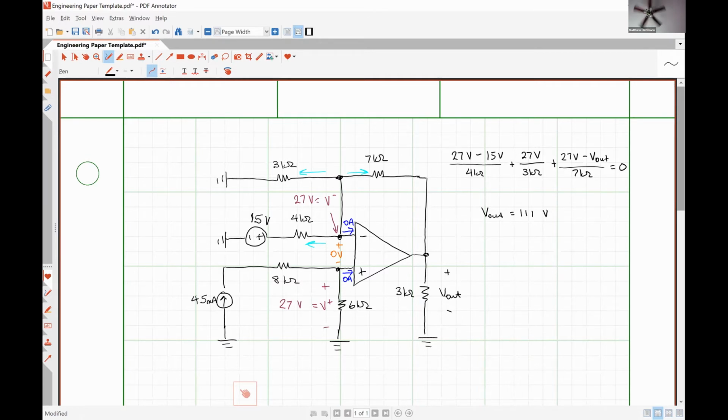But it's all based on just these simple applications of the ideal op amp rules and then doing nodal analysis. And when we do cascaded op amps, I guess that would be next Tuesday, that's where we string multiple op amps together. It's still this basic process. It's just identifying the voltage at the non-inverting input terminal, mirroring that voltage at the inverting input terminal, and then performing nodal analysis to figure out your relationship to your output voltage. The steps are the same for all negative feedback op amp circuits where you're using the ideal model.